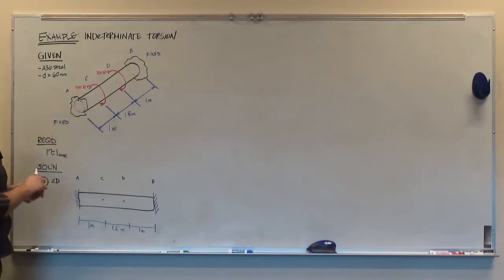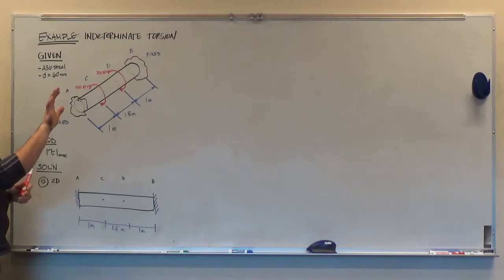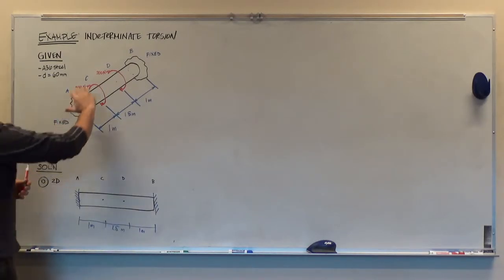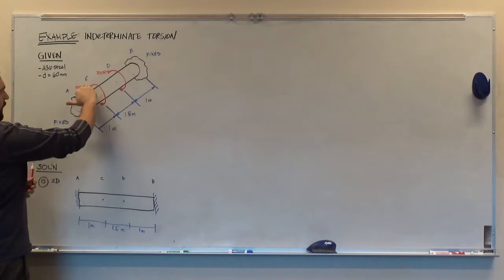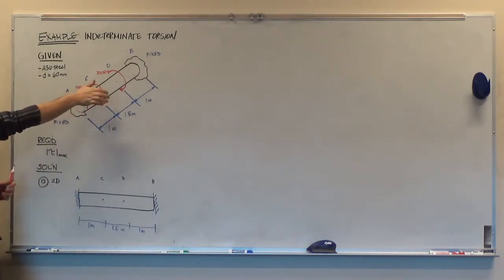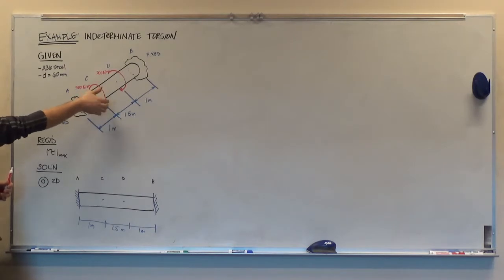So we take our right hand, we rotate our fingers in the direction of the rotation that's shown, and whichever direction our thumb is pointed by tracing that moment is the direction of the two-dimensional vector that represents that moment. So here, this would not be the correct direction. This is going the opposite direction of the rotation. I have to turn my hand upside down for my fingers to curl in the direction of the shown rotation or the shown torque. And so here, both of these have a vector with the sense to the right.